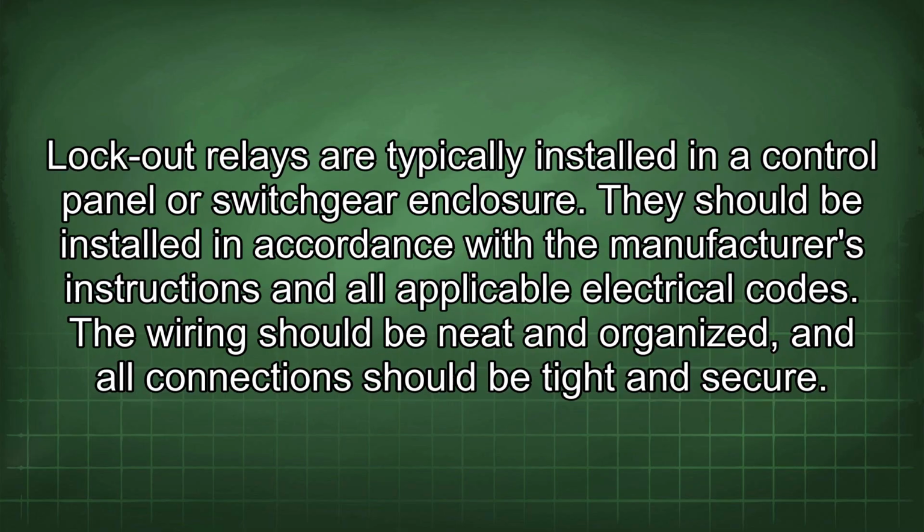Lockout relays are typically installed in a control panel or switchgear enclosure. They should be installed in accordance with the manufacturer's instructions and all applicable electrical codes. The wiring should be neat and organized, and all connections should be tight and secure.